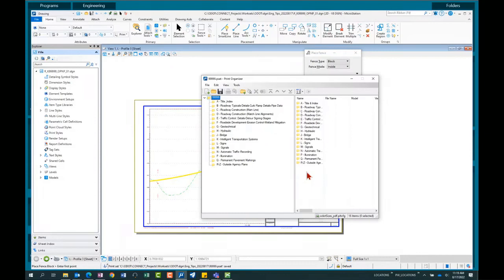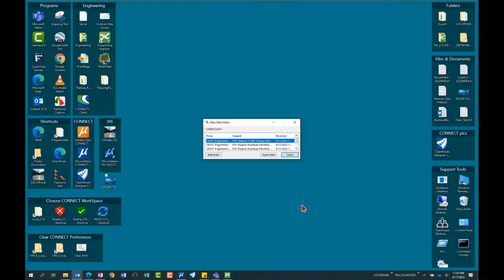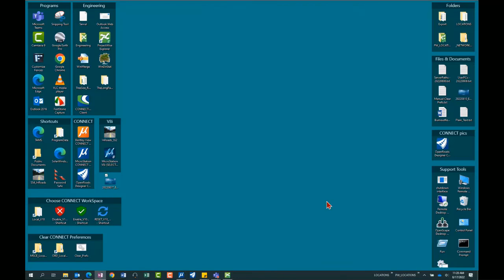You load the seed read only if you're not working in ProjectWise, and then you can populate this. Now I'm going to switch over to working inside of ProjectWise because I want to show you how to create this keynew.pset, create that new PSET file using the ProjectWise resources. I'm just going to minimize MicroStation, and I am going to use ProjectWise Explorer.